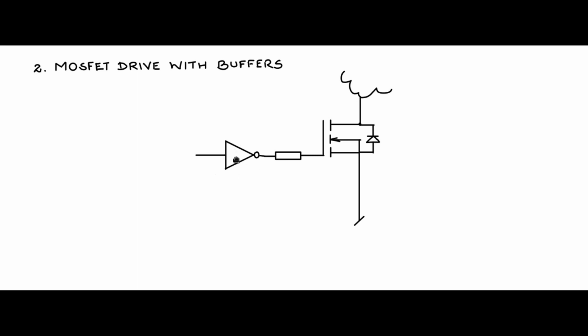Or you could use an inverting buffer like the CD 4049 and apply Vg at the input. When you apply an inverting Vg pulse, when the pulse goes low, the buffer output goes high and pumps in the gate charge and turns on the MOSFET.